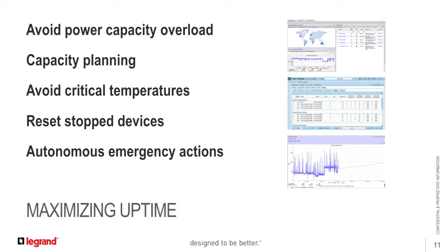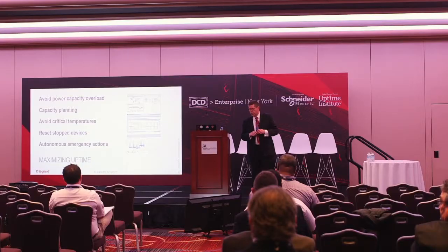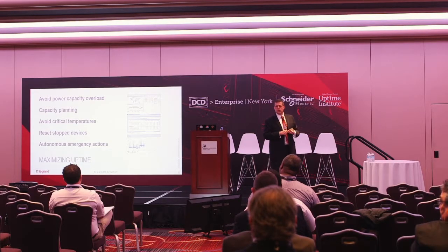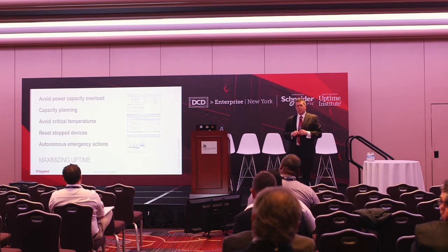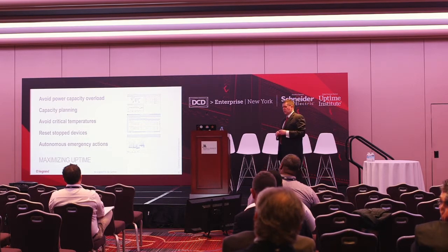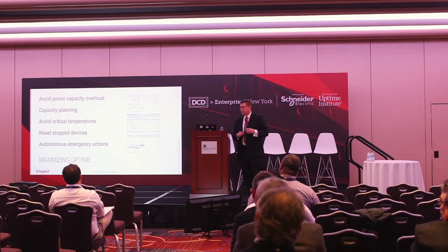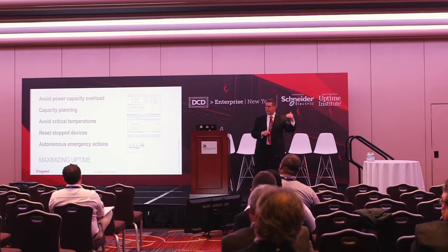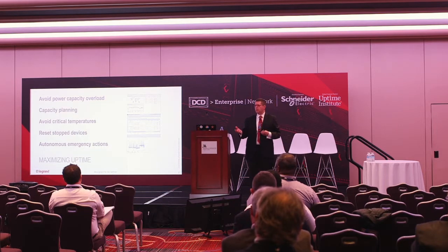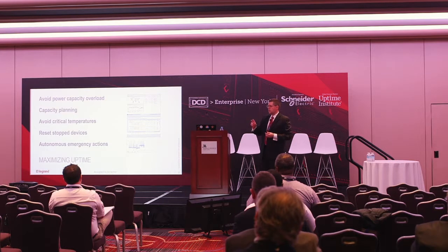And you want the system to have a graceful way of shutting itself down in the event that conditions dictate. So for example, the grid went down, your genset is running out of gas, then you need to execute a graceful shutdown so that you have a known state in all of the hardware that's deployed.